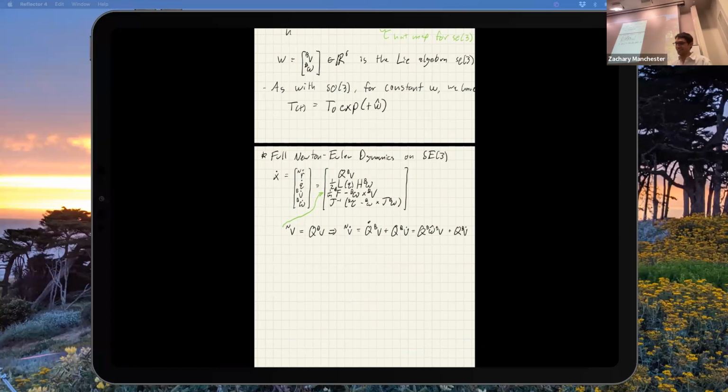Cool. And the last thing to remember is that this V dot is A in the inertial frame. So F equals ma in the inertial frame, right? So I'm now going to write down, this whole thing equals 1 over m times F in the N frame. So I just wrote down F equals ma, and then I went through all those gymnastics to write it in the body frame, and I picked up that extra term, right? So if I want to write the whole thing in the body frame, I'm just going to massage that around and solve it for V dot in the B frame. This is the guy I want, right? So I'm basically going to move the Q's over.